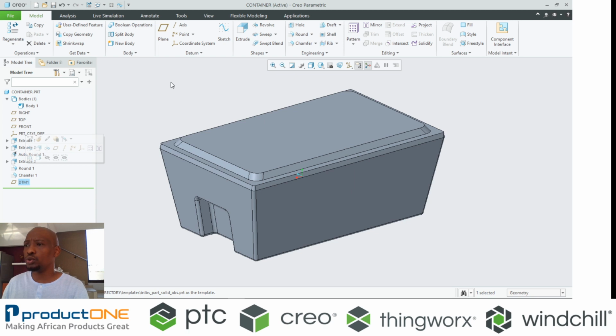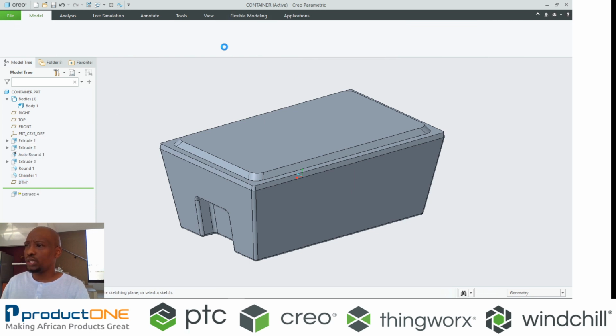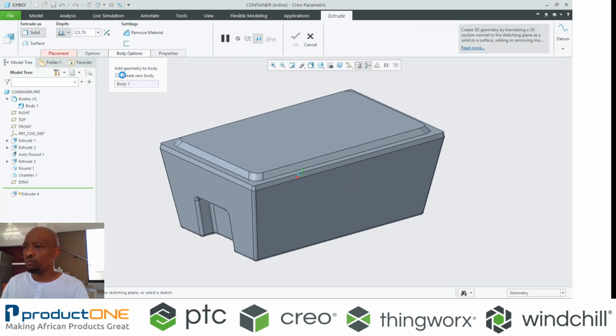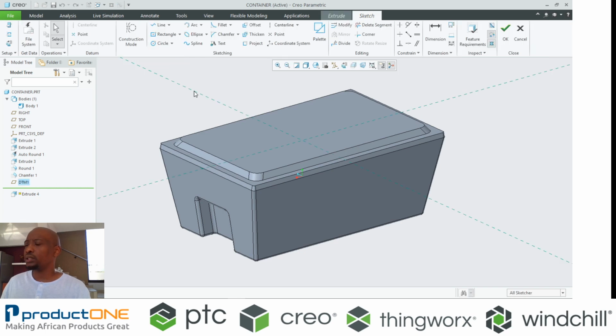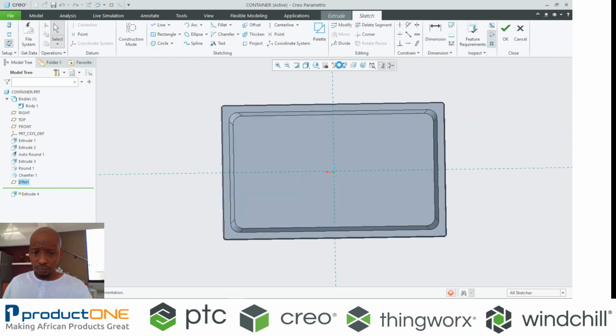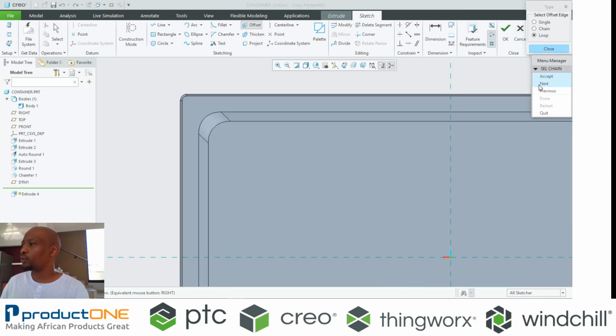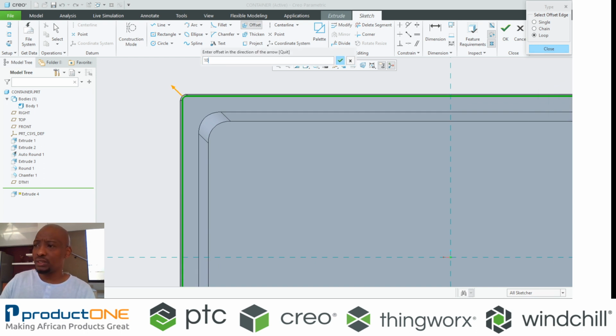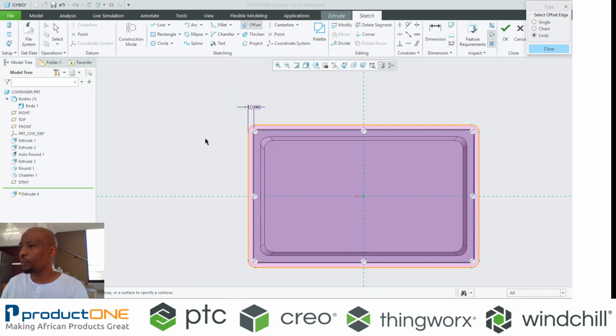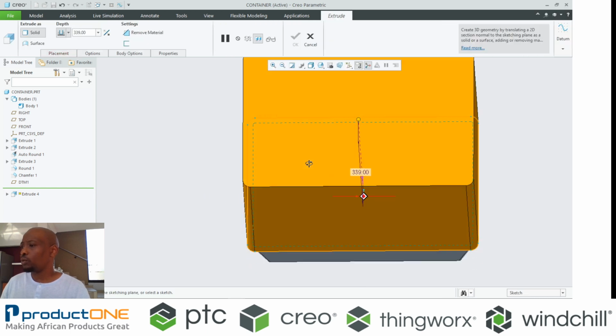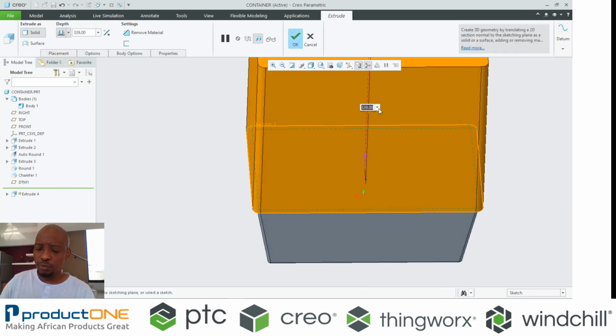Now, what I'm going to do is create a brand new body, and this is now what I need to do. I'm creating a lid for this. So I'm going to say this is my point of reference. I can choose, of course, the offset distance on these. I'm happy with that. And what I'm going to do here is specify the length of this item.